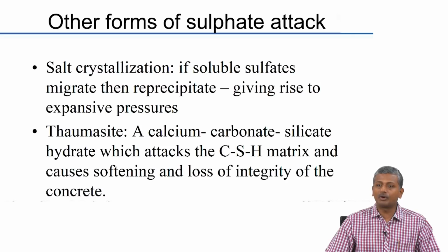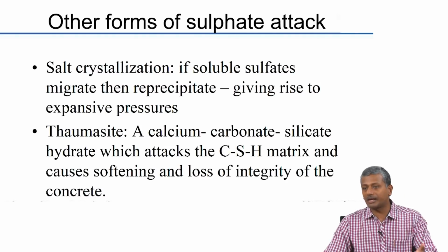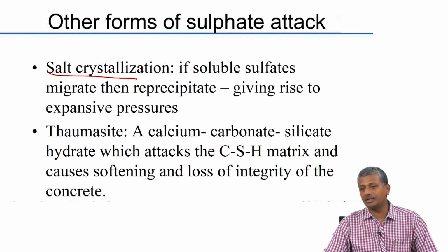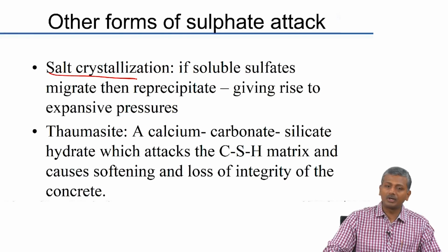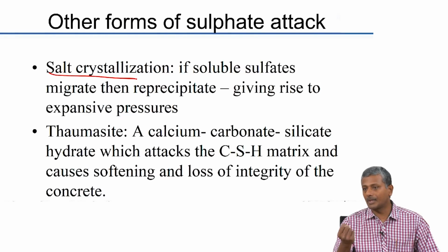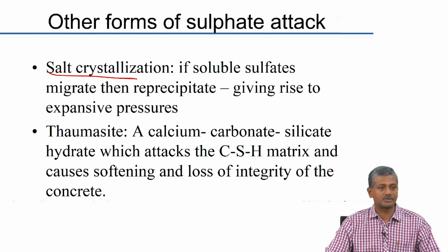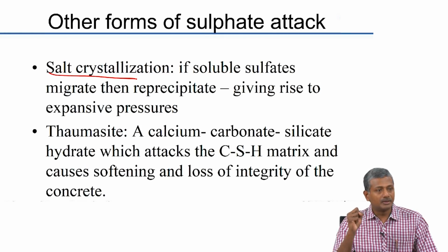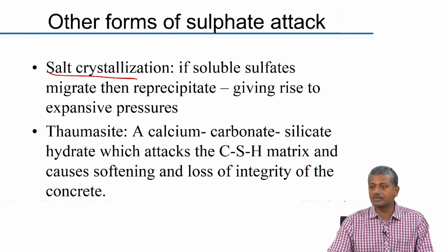Now, there are other forms of sulphate attack also. We have talked about external sulphate attack, internal sulphate attack, primarily related to ettringite formation, but then you can also get salt crystallization. If you have drying and wetting, the salts that are getting deposited by the water in the porosity start crystallizing after the water dries out. Again, this can happen because of sorption, wick action, all those kinds of things can make this problem even worse, because of which you have salt crystallization. And this crystallization happening in fine porosity of concrete can create crystallization pressures, and that pressure will break open the concrete. So, again you have salt crystallization damage.